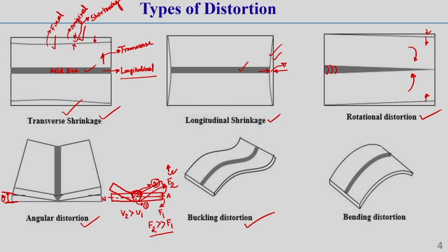That means the buckling phenomenon, you are well familiar with this, because during shrinkage time some sort of shrinkage force occurs. Due to this shrinkage force there is a chance of longitudinal shrinkage. What I am telling, understand, due to this longitudinal shrinkage, and due to the thin section and lower critical length and higher critical length of the plate weld length, there can be a chance of buckling of this thin sheet or thin plate. So, buckling means it fails due to this shrinkage effect, especially the longitudinal shrinkage effect.